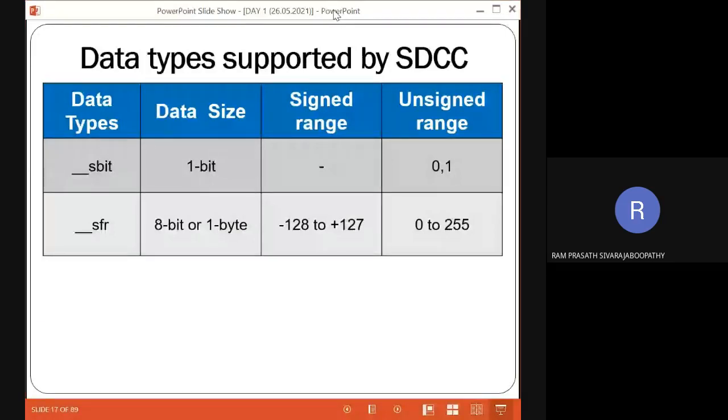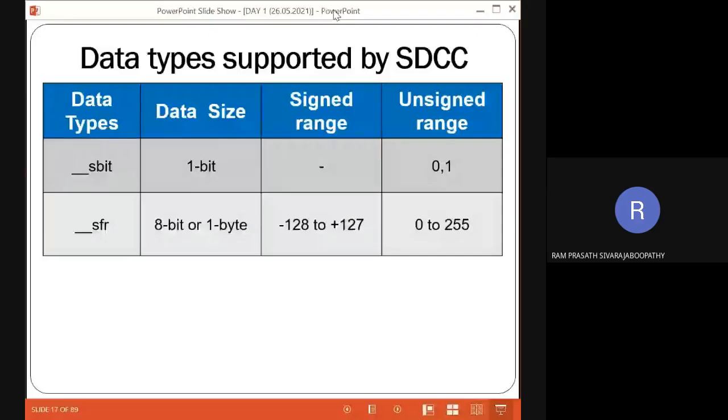For an embedded C program for a microcontroller, the very first step is to include the header file, which is going to have the register definitions for the particular microcontroller. Which register is at which address, and what naming will be mapped, is done using these two data types. This is not available in the case of a normal C program. So these are the slight variations we have in embedded C from a normal C program.